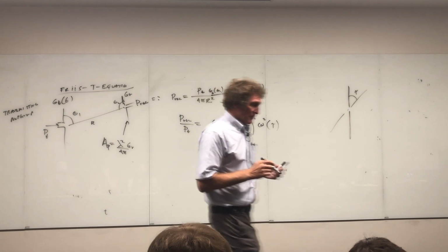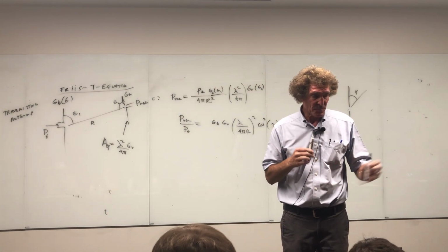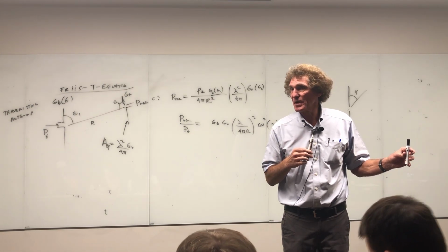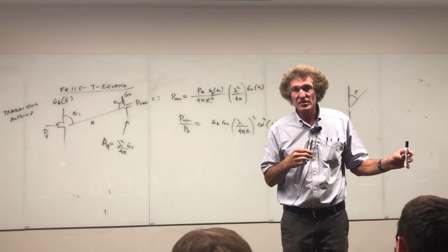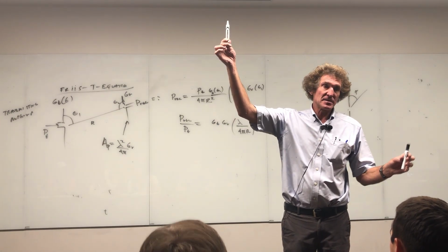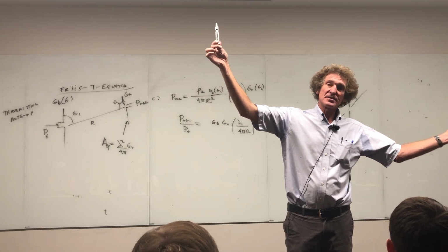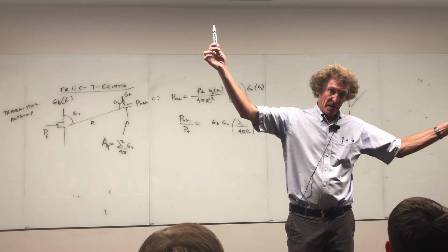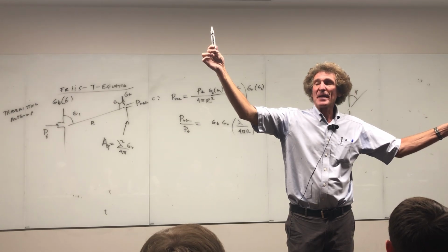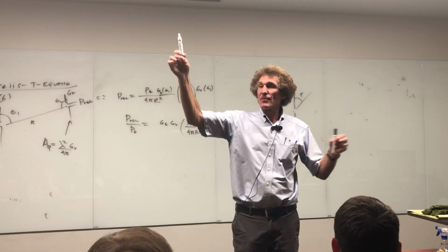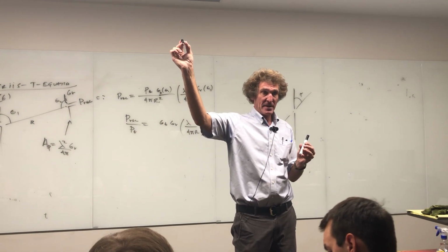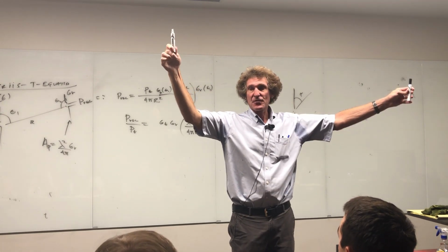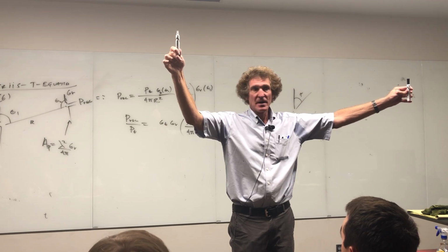That's important to know. But the problem with a lot of this stuff is that so much these days with small companies, when they actually string antennas and do stuff, they have people doing it that aren't fully aware of some of the problems. So they'll mount an antenna like this, and a couple miles away they'll have an antenna like this receiving, and they don't get anything. Well, for starters, they're not aligned. That's important. And also, by the way, if you want the maximum amount of signal received, then have it vertical, perpendicular to the ground, not planar to the ground. Don't have it horizontally polarized, make it vertically polarized, and try your darndest to get them aligned if you're making any kind of thing where you're communicating short range.